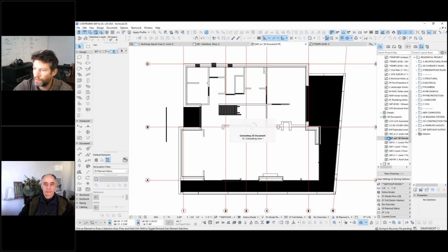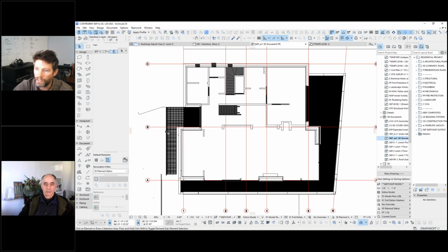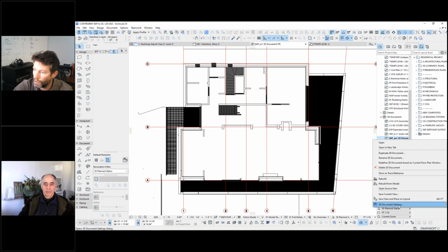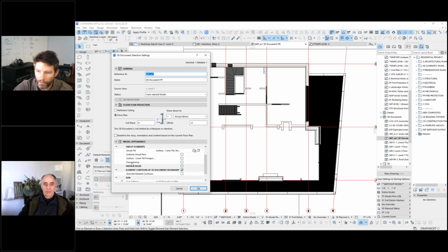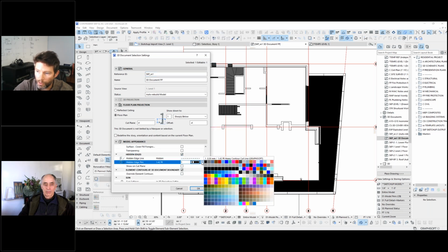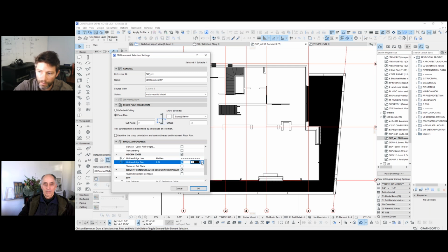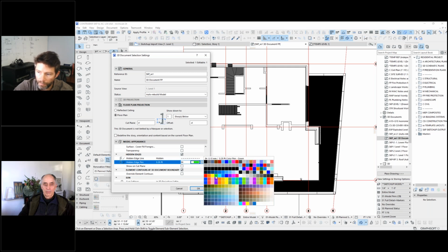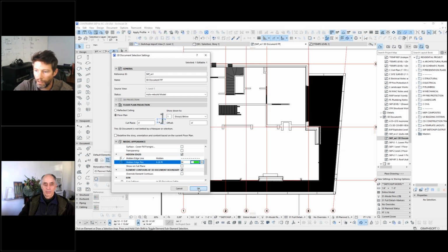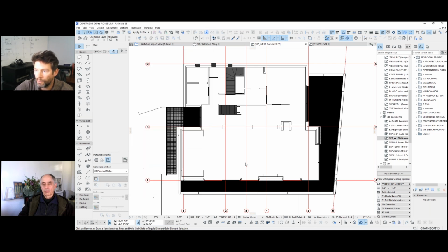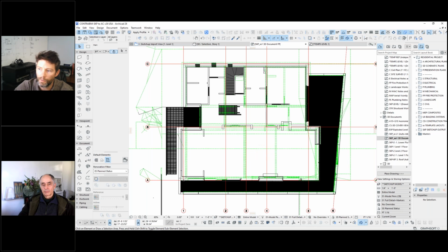So it's generating. So yeah, it did pick up content down below, but I needed to toggle those hidden edges, and then we can of course give it some sort of override here. So we'll make it something that's very different. We'll go like a dash green. So we click that, and we should see some hidden lines of everything down below.